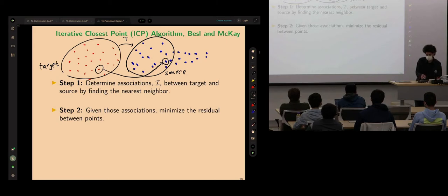Well, the question is more basic: do we know what corresponds to what here? The sensor is giving me a point cloud, I move, I get another point cloud. We don't. So there is no way to know what point corresponds to another point. There might be some problems with association if the structure is symmetric. Symmetry can cause problems as well. But ignoring everything here, we do not know what point corresponds to another point.